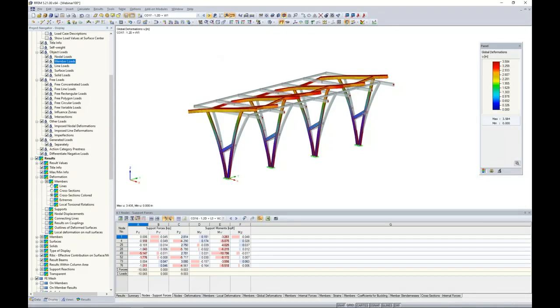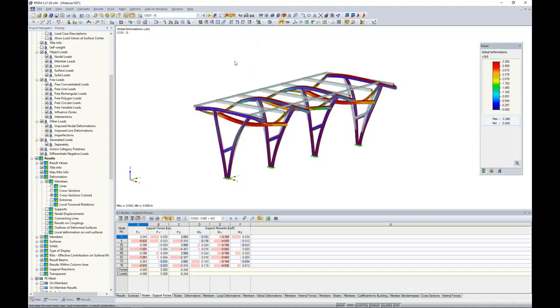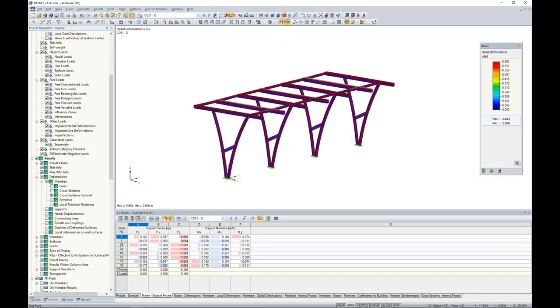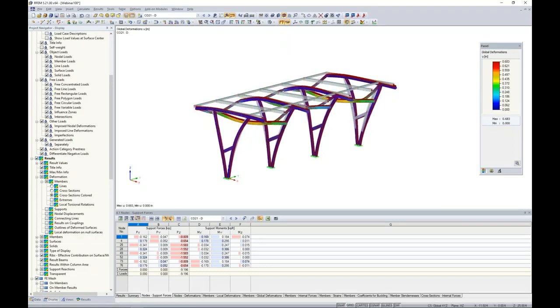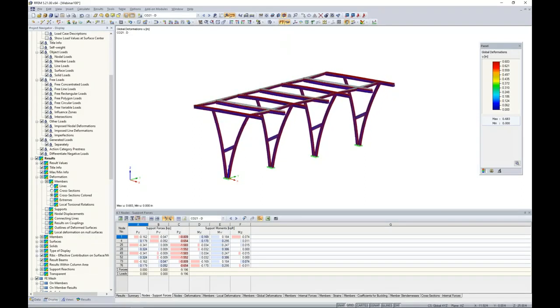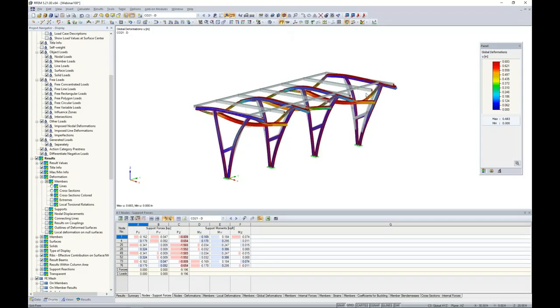And now I can scroll through to my different load combinations just to see the reaction of the structure under the different applied loads. And if we're also interested in seeing how the structure behaves as a short little video, we can play the animation here. And how I think this is useful is that if we incorrectly modeled something, we'd probably see some odd deflections here for this video. So just a nice feature that we can export this out, of course, and save to our computer as a video file as well.